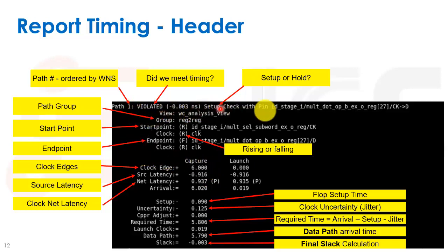And I went over in the lecture all of these different points of how to read such a timing report, both for setup, for hold, when we have the full clock, and so forth. Just the question over here was, what is the clock period? And Cadence, at least in their newer type of Innovus timing reports, it's a bit cryptic. It doesn't say actually what the T is over here. What it does have is this thing that says clock edge, and we see that the launch clock edge happens at the time 0, and the capture clock edge happens at the time 6, and therefore we can know that the T equals 6 nanoseconds.